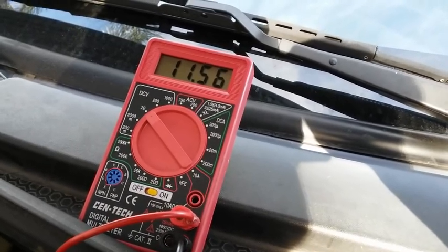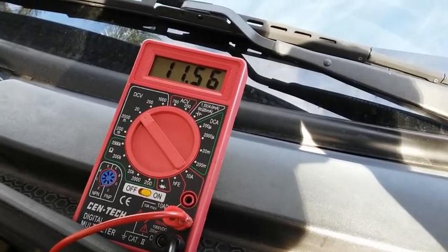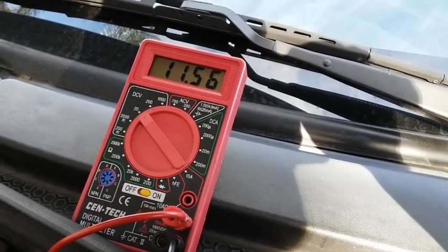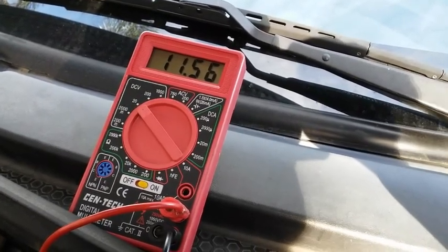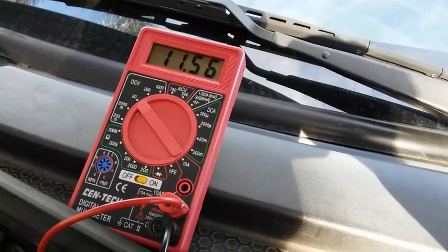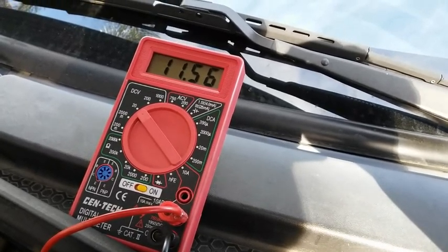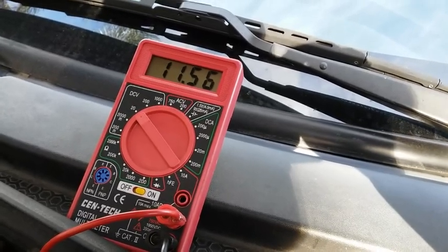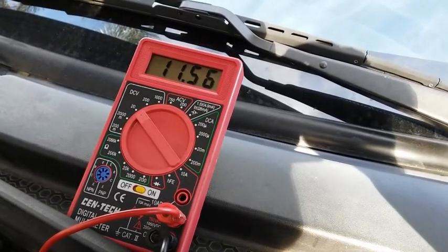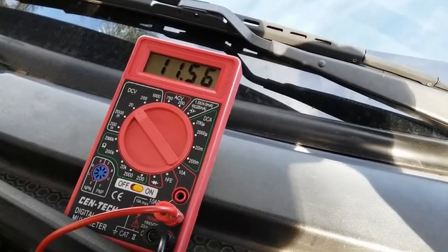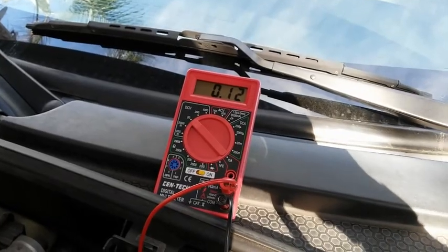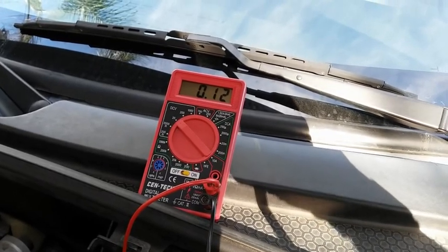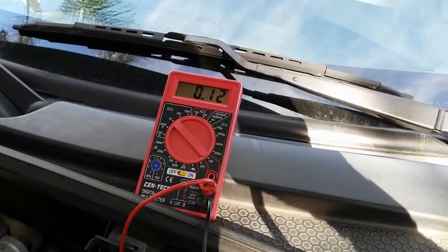Alright, the next step is to plug the connector back into the oil pressure switch and then start the engine. Remember, when there's pressure on it, this circuit goes from closed to an open circuit, which means the contacts have opened up, and this voltage should remain approximately 12 volts. The connector is already connected back into the oil switch sensor, so the next thing is to start the engine.